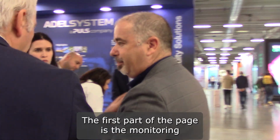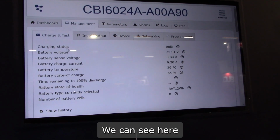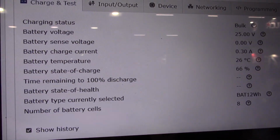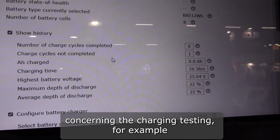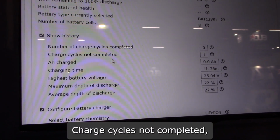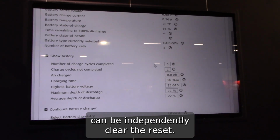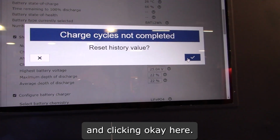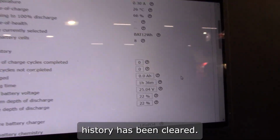The first part of the page is the monitoring of the charge and testing part of the device. We can see here the charging status, battery voltage, battery charge current, and so on. Plus, we have some history information here concerning the charge and testing. For example, the number of charge cycles completed, charge cycles not completed, highest battery voltage, and so on. Each of these histories can be independently cleared and reset by clicking on the value and clicking OK here. As you can see, the charge cycles not completed history has been cleared.